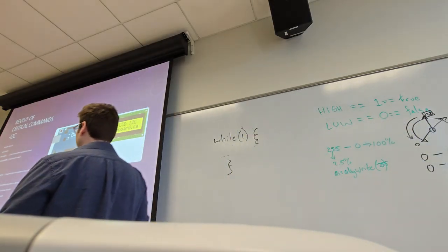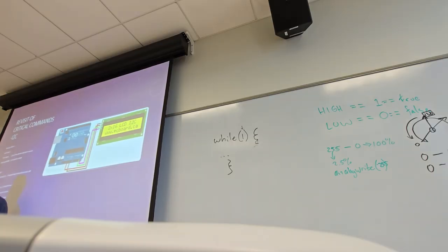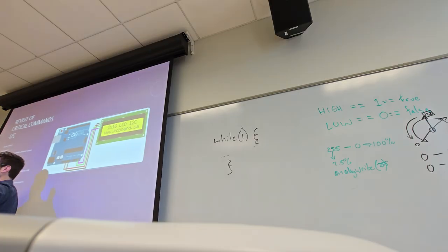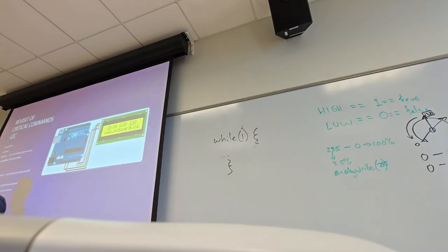So our void loop, fun fact, again, is that behind the scenes somewhere there's something that defines what the loop function is, and it's just a while loop that, once we hit it, we're in there forever and evermore. We just keep cycling through. Sometimes, though, we want to wait for something. While no data, for example, is a very common thing. Or while we are connected to the bus still. Again, another common thing. In this case, it's while we have data available for us to read.